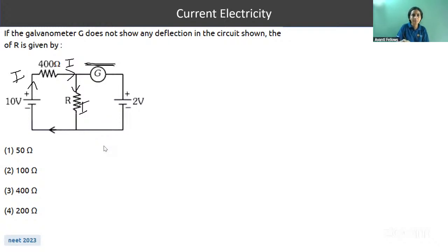Second thing, there is a battery connected here, 2 volt, and this is in parallel with this, because in between there is nothing across which potential drops, because G has no current flowing through it. It means if current were flowing through it, then there would have been a potential drop. How much? R_G I', whatever current would have been here, right? There is no current. It means this value is zero, no potential drop.